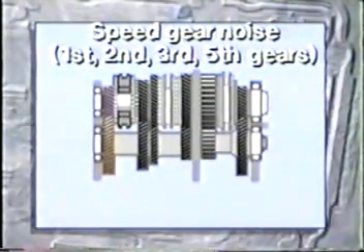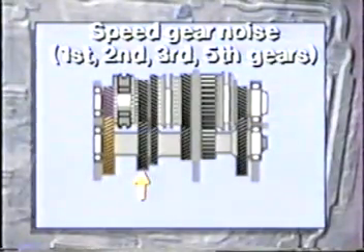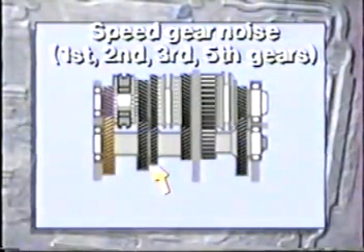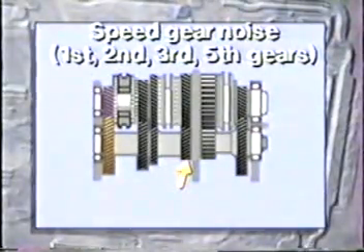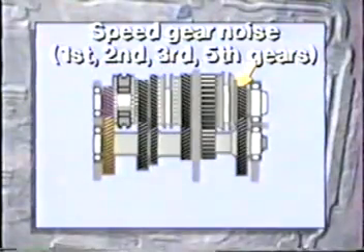Gear noises are usually the easiest to identify. They normally occur only while driving in that gear and will be most pronounced either while accelerating or while decelerating, depending which side of the gear is affected. Carefully inspect the corresponding gears on both the output shaft and countershaft.